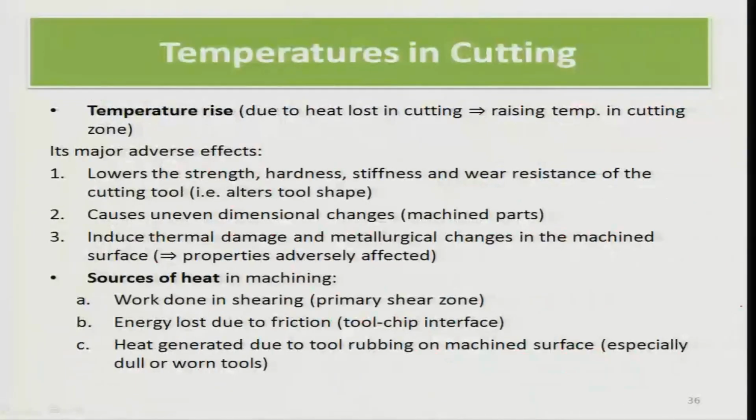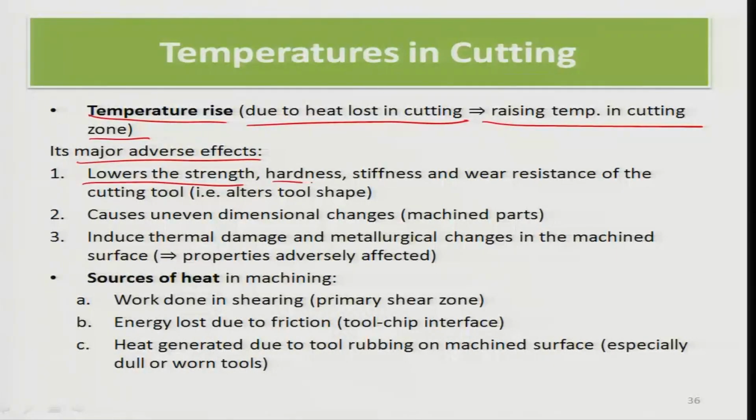We also need to explore the temperature rise due to heat lost in cutting, and I think I had theoretically modeled this earlier and also helped you solve numerically the temperature rise in the cutting zone. The major adverse effect of a temperature rise is that it lowers the strength, the hardness, the stiffness, and the wear resistance of the cutting tool itself.